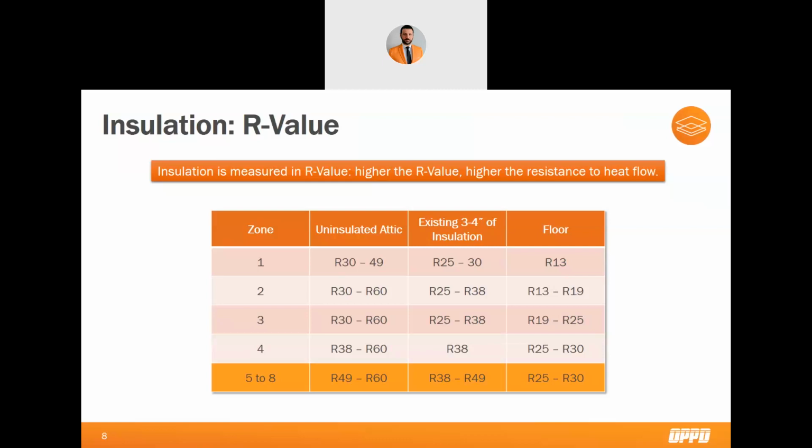Going back to the attic insulation recommendation, I want to address something about adding to existing insulation already rated at R49. If your attic has already R49 insulation in it, it is not necessary to add insulation to get it to R60 when it comes to the energy savings of that measure. If you don't have insulation or are fully replacing your insulation in the attic and want to go straight to R60, you can, but the upgrade of adding to R49 does not have a significant payoff.